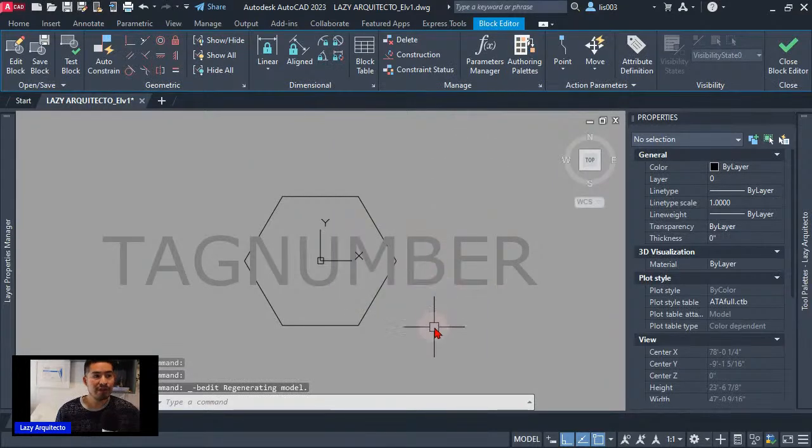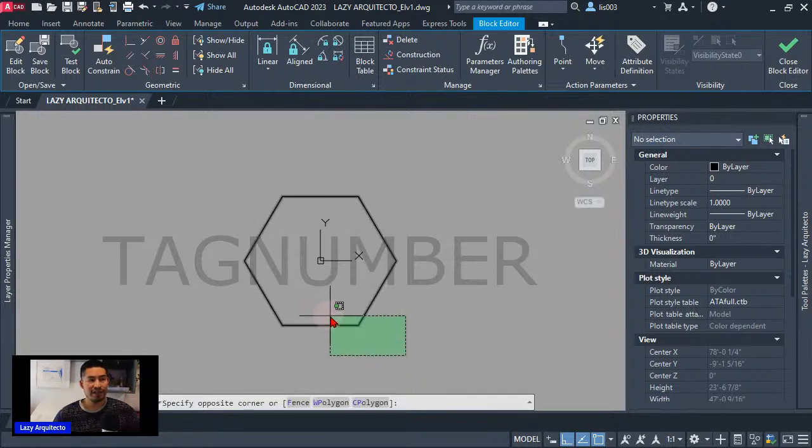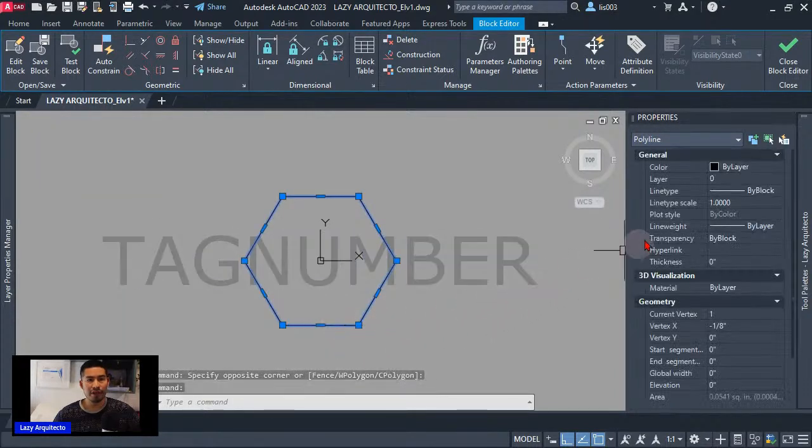So over here, again, if we check some of our properties, so let me select this, right? And if we go to the color option or layer first, we can see that it's on layer 0, and that's correct, right? Because we just talked about it, that this should be 100% on layer 0, right?